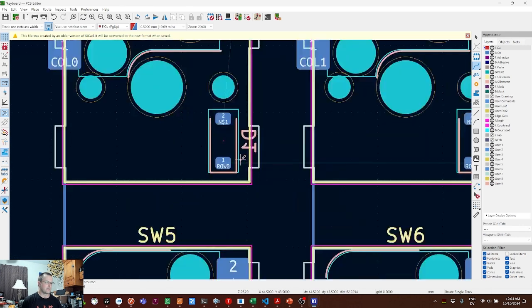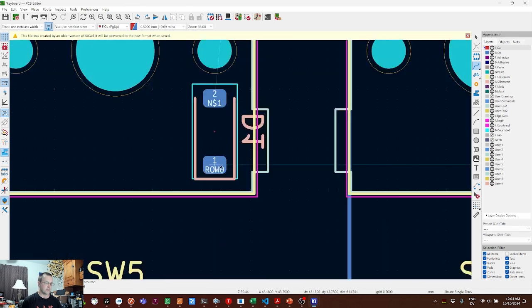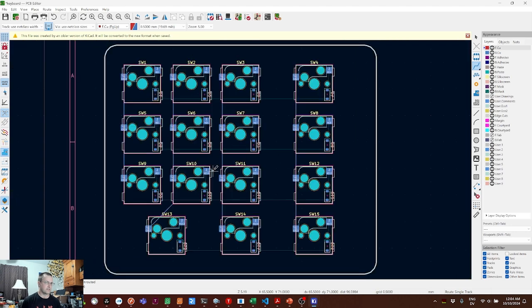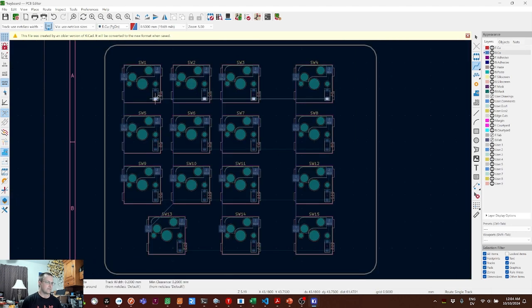We can do the same thing with the rows, which have smaller labels, but you can see them labeled here on the diodes. We'll click here, drag across to the next one, and KiCad seems to be trying to take a shortcut. We want to go, yeah, it doesn't want to go across there. Well, there's already a trace in the way. Remember, our column trace went from there to there. And on a two-dimensional board, we can't just jump over that other trace. But our board is not strictly two-dimensional.